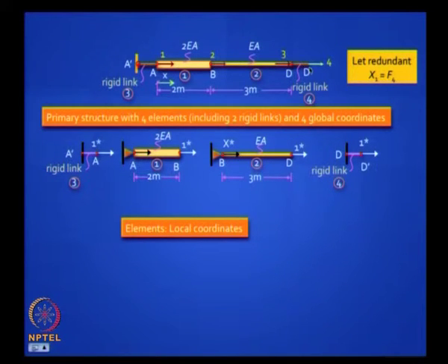is the force at this end here, which I call x1, okay, which is a reaction in the other support, and it follows that the internal force in this element 3, okay, this internal force, it is positive if it is tensile. Do you not think it will give me the reaction pointing this way? Let us say I get 20 kilonewton, that internal force is my reaction Ra pointing to the left, then only I get tension. Let us say I get minus 20 kilonewton, that means Ra is pointing to the right.